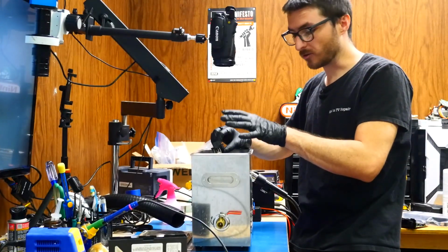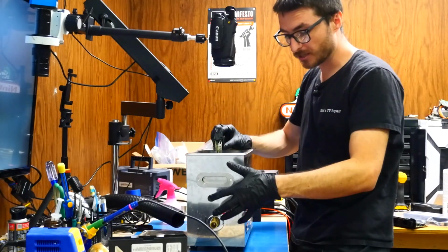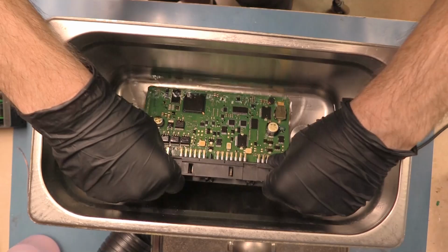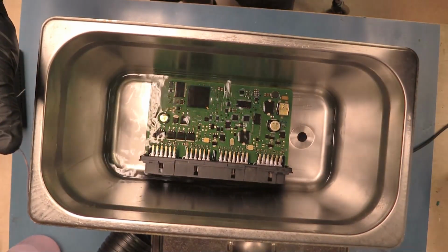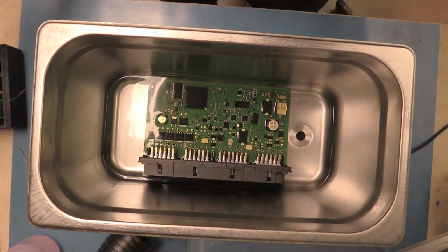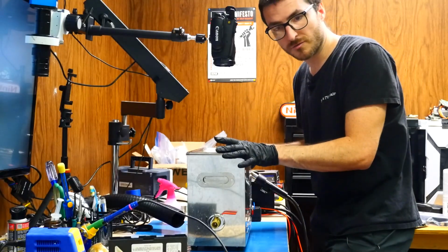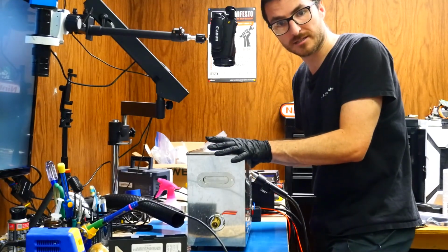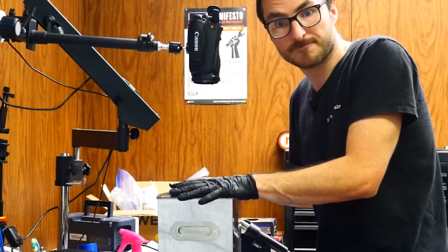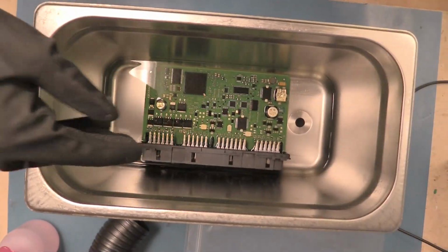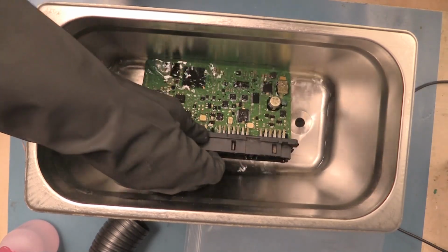So I'm gonna be using an ultrasonic cleaner. Now I'm not actually gonna be using the ultrasonic cleaner feature, but just the fact that it's a metal bin. And we're gonna go ahead and put our board in our conformal coating remover. Now there are a lot of fumes and this thing does evaporate, so we'll cover it up. And usually you do wanna do this in a very well ventilated space because you don't wanna be breathing this in. We'll let it sit for about 45 minutes to an hour and then come back and check in on it. All right, it's been about an hour or so. Let's take a look.